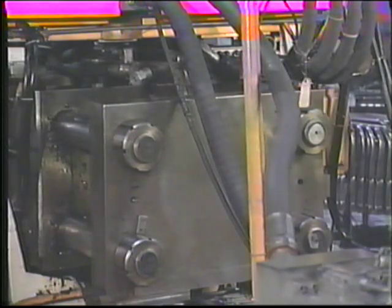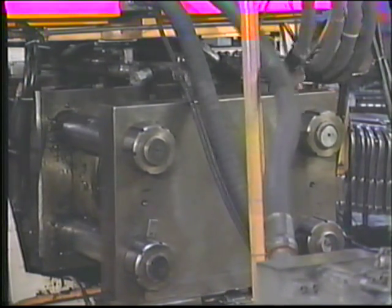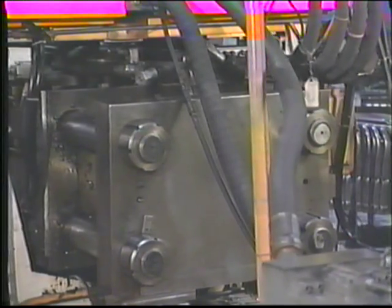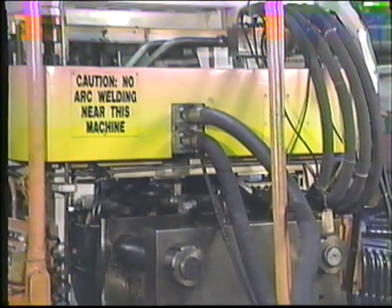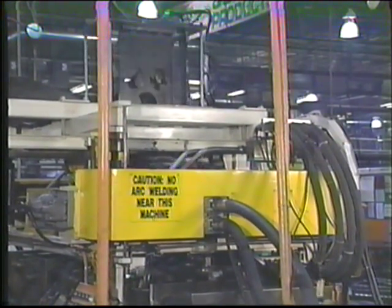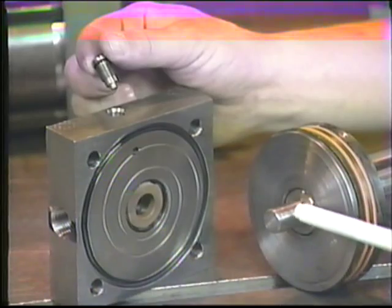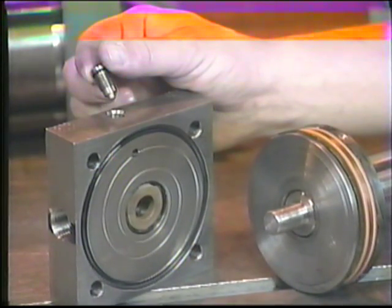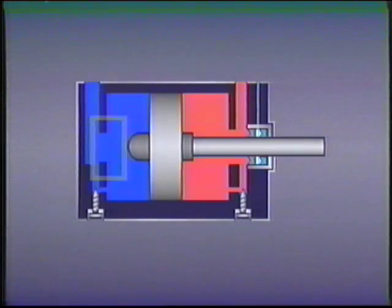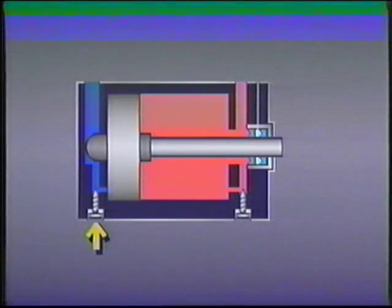Another potential problem with cylinders is hydraulic shock. Sometimes this shock can be severe enough to damage the cylinder. Many cylinders include a cushion to slow down the piston as it approaches the end of its stroke. This reduces the shock and helps prevent damage to the cylinder and the system. The cushion may consist of a needle valve in the end of the cylinder and a plug or spear attached to the piston. As the piston nears the end of its stroke, the spear blocks the opening, forcing the fluid left in this area out past the needle valve. Adjustments of the needle valve determine the extent of the cushioning action.